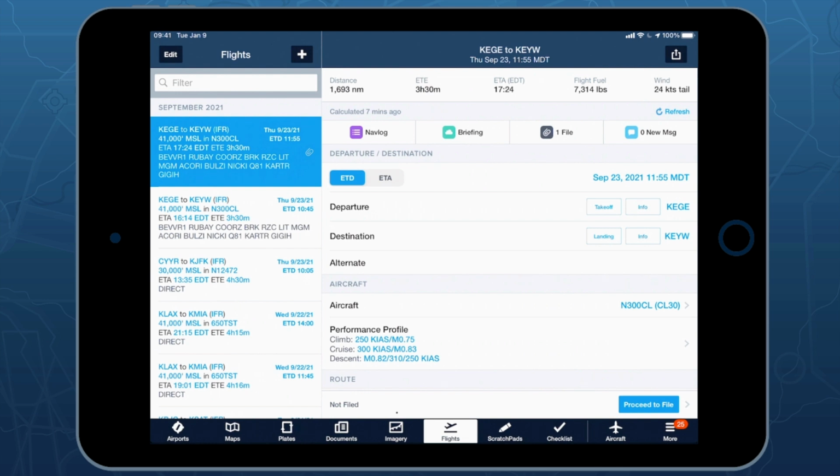Prior to landing, usually prior to top of descent, I go back into the landing data tab for the destination, and I put in the actual conditions to get not the planned performance, but the actual performance. Of course, the FARs largely require us to use planned performance, but in the real world, I want to know what my actual performance is. So I tend to visit the landing page prior to top of descent, and hence split my usage of those 2 views.